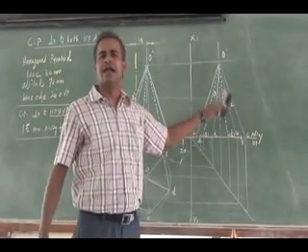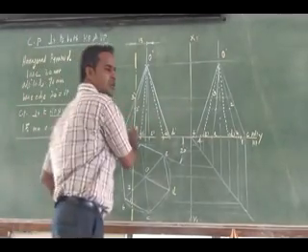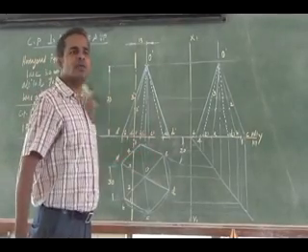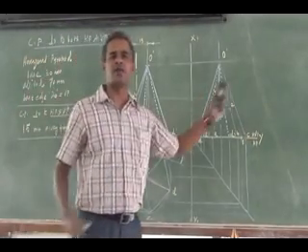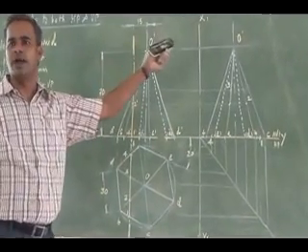Since you are going for a left side view, you show the cutting plane to the left side of your axis. If you are going for a right side view, you represent your cutting plane to the right side of your axis. Then only you will get the true shape as a visible one. Otherwise, the cut surface will be a hidden one.